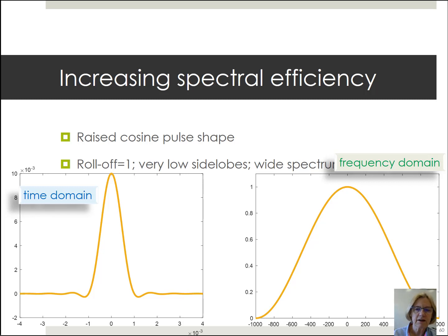But what's interesting here is that we have a way of trading off, and in this trade-off, we're looking for very time-domain-isolated pulses, very small side lobes, so that the intersymbol interference would be almost negligible. But in the frequency domain, if we have to share our frequency domain with other users, of course, we risk having impairments coming from crosstalk rather than impairments coming from intersymbol interference.